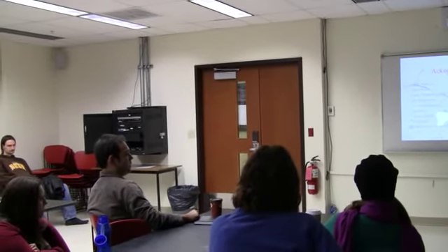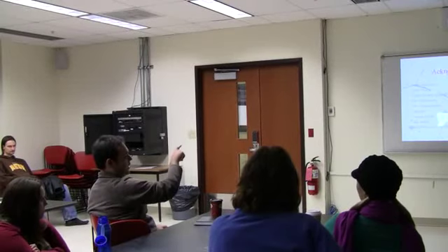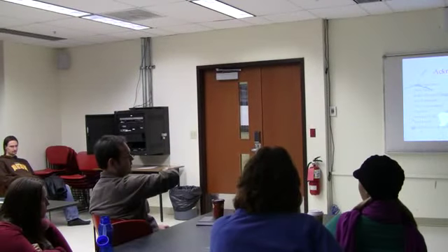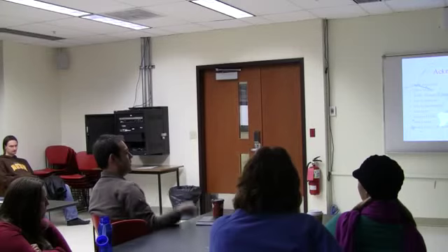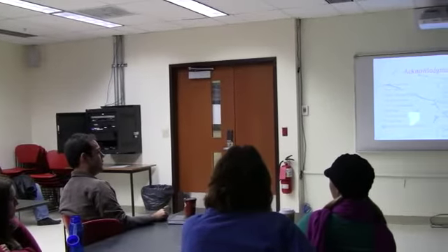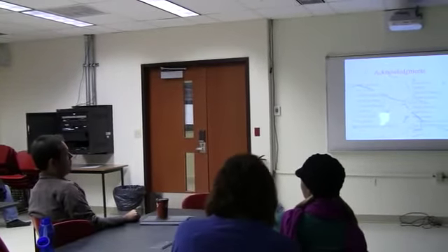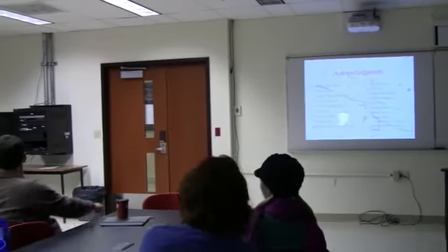I'll see if that might make a difference. Because it looks like a lot of your points are a bit higher on your areal ones, so I think if you were to do that, it might actually improve the data. Yeah, okay, I'll try that. Most metrologists, there is a correction factor you can apply from 2D to 3D, just doing grain size analysis. It's the same idea, but there is a correction factor. I would imagine it's between 1 and 3 halves of the power.